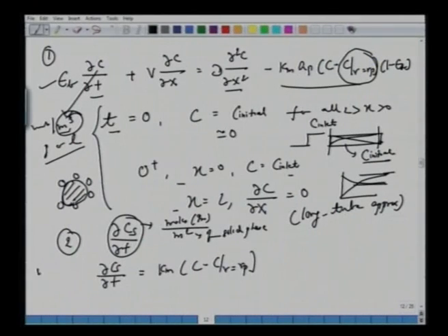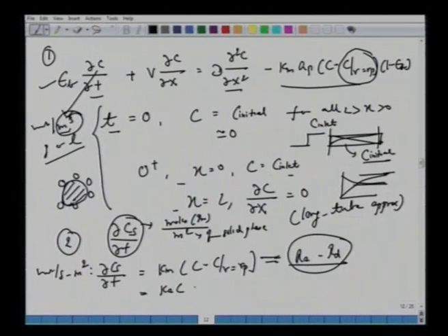So it's moles per second per meter square, and this will also be equal to some rate of adsorption minus rate of desorption. Okay, so we were talking about all those isotherms, Langmuir isotherm, Freundlich isotherm, etc. We have this type of situation. The most common would be first order adsorption and first order desorption. This would be the simplest of these.